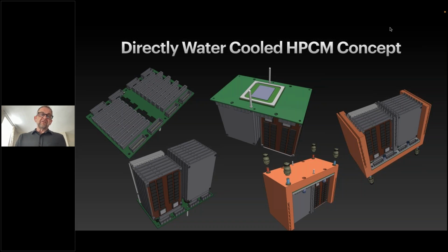In the bottom left, you can see a bunch of E3.S and a NIC 3.0 populated in the module, with one of them open. That was an OMI one that we designed when I was with OpenCAPI. As you look to the right, you see the orange enclosure, which is the water-cooled enclosure. We're innovating a little more around it, but the idea is that everything is directly water-cooled. There is no air. Ideally, you would be insulated from the air, and the only way out for the heat from all the devices would be through the water, so you get an efficient transition into the water cooling.